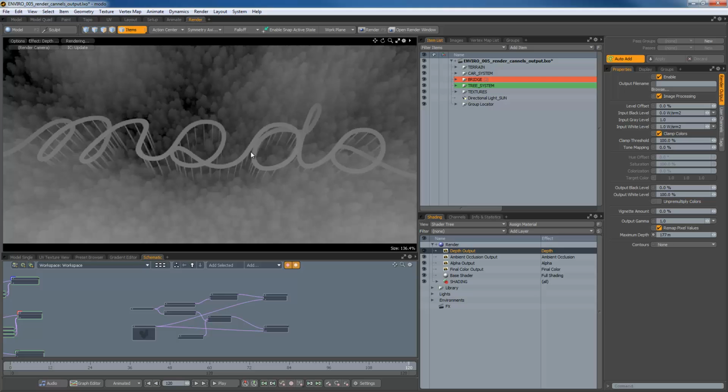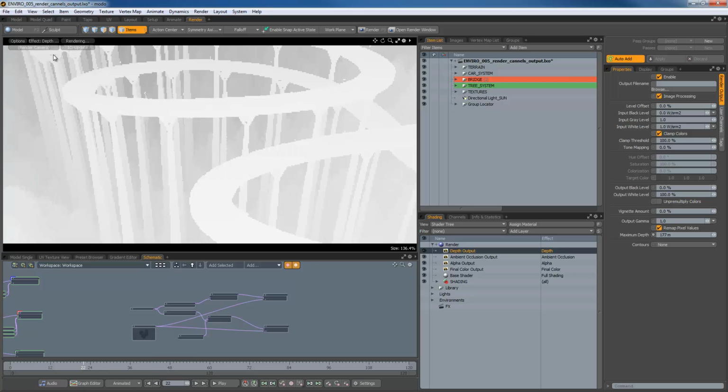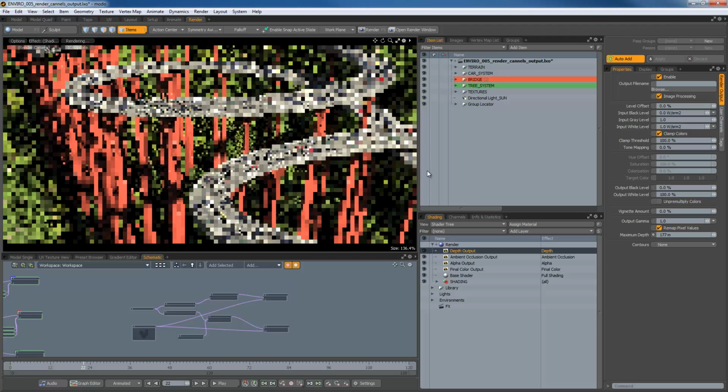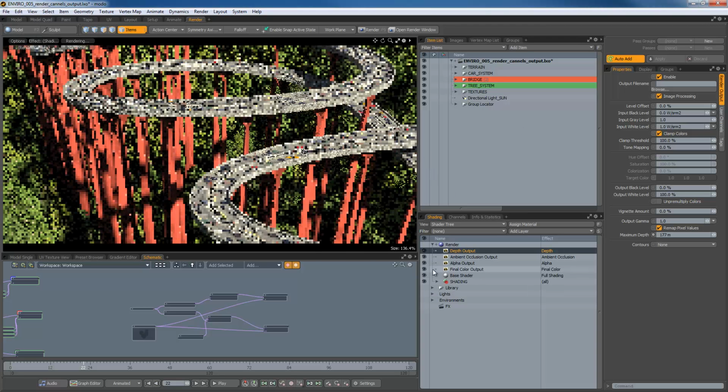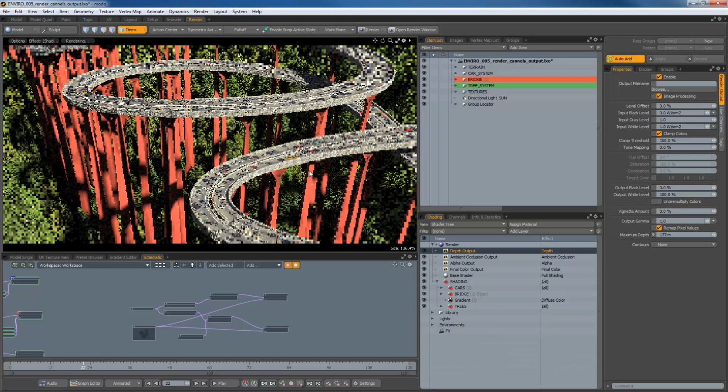Now, in compositing, we are using masks quite often, and in many cases you would like to essentially generate mats for individual objects in your scene. That can be achieved in Modo also quite effectively. Let's just go to the shading, and all you really have to do is pick a shader. I mean, that would be one way to create the masks.